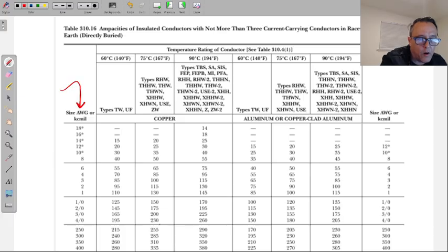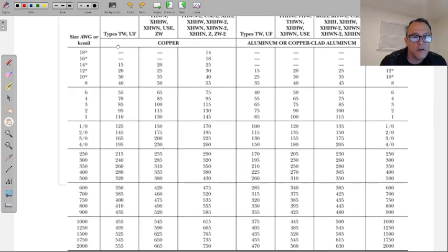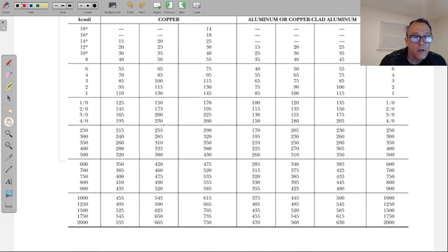But these are all of our wire sizes, or what we call wire gauges. All right, that's what that G right there stands for. It's called American Wire Gauge. That's the system that we use to gauge wire, just like you gauge metal. If you've ever worked with sheet metal, it has gauges as far as the thickness of that metal. So all of these numbers here on the side represent the thickness of each of the conductors that we have.